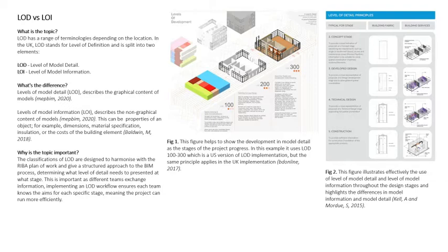To give some background, LOD was introduced within the BIM Protocol, released by AEC UK in 2009, as Level of Detail within its model development methodology. In 2013, the PAS specification for information management for the delivery phase of construction projects using BIM, now replaced by British standards EN ISO 19650, introduced Level of Definition as a new classification system with 7 levels to include both aspects of Level of Model Detail, LOD, and Level of Model Information, LOI.